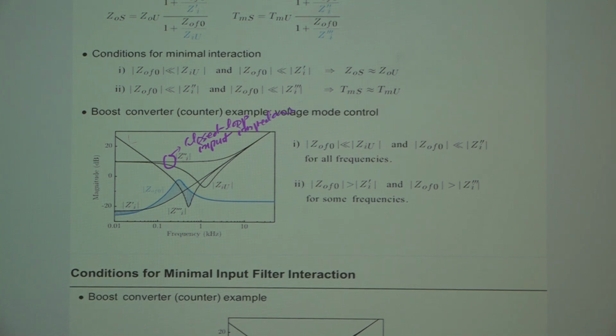Okay, and the other two, these are open loop input impedance. One is just simply open loop impedance. The other one is open loop impedance with output shorting, right? So you cannot close the feedback loop. This is the definition of the open loop. This is the definition of input impedance. Measured under this condition, that is the requirement that comes from the EET, right?